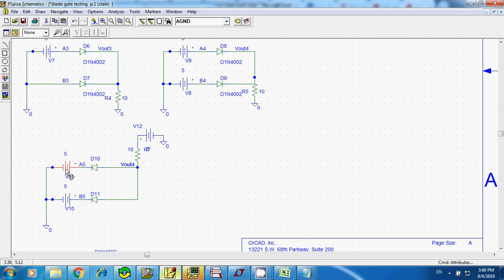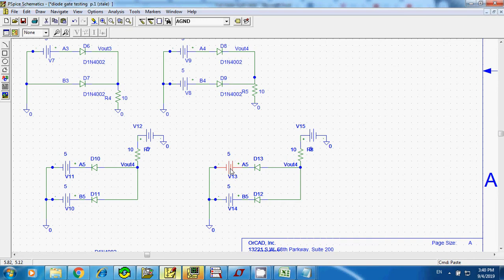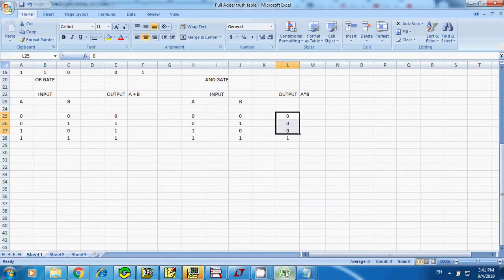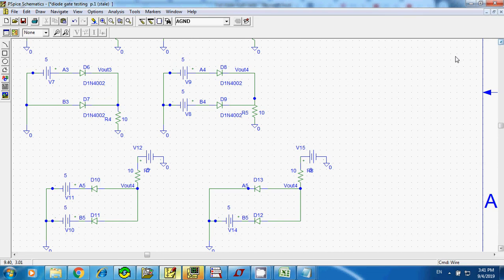Now in the case of you have the input to be low or 0, that means the voltage at this point is going to be higher than the voltage at this point. So that means your diode is going to be on. So when it's on, your 0, or your ground, is going to connect directly to the ground and pass that 0 to the output. So your output is going to be 0 whenever they have 0 here. Whenever a diode is on, that means your output is going to be 0. Correct? So that's how it works. You can explain later on for the case of the logic combinations of 0, 0, 0, 1, 1, 0, and 1, 1. Okay? This might seem a little bit complicated, but you apply your logic to analyze how to create digital logic gates using diodes.